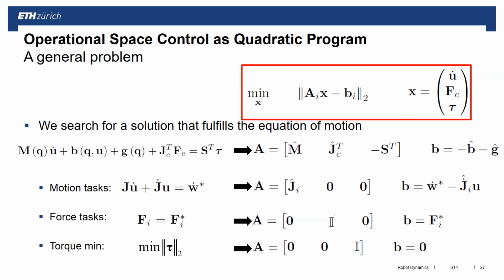So for every step, I have a null space, and I try to fulfill the next task as well as possible in this null space without violating that task. That was the most generic setup or formulation that we came up with at the very end. It can be done for inverse dynamics, and it can be done for inverse kinematics. It's the same. All we change here is my x and then also the A matrices. And with this, we're stopping for the first part and we continue in 10 minutes.